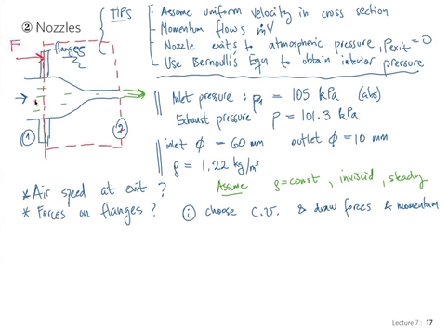But we also have a pressure force in this case. This problem has, in addition, P1 times area. Because the pressure on this side is not atmospheric, it's different than atmospheric, okay? In the previous control volume, it enclosed the whole rocket and the jet was at atmospheric pressure. So the whole surface of the control volume was at atmospheric pressure.